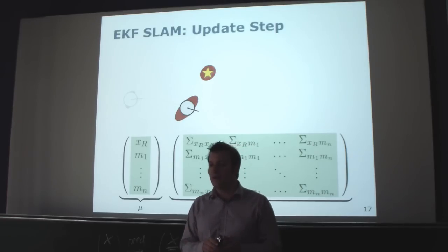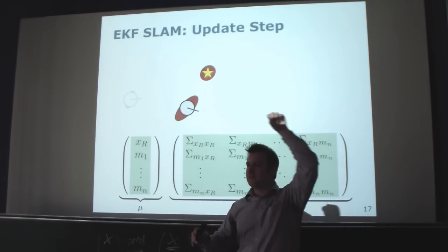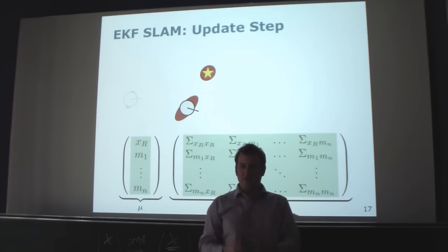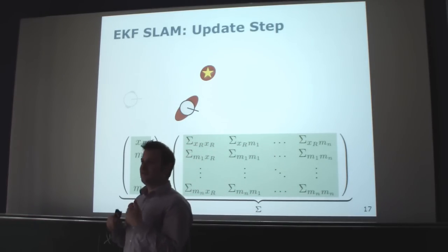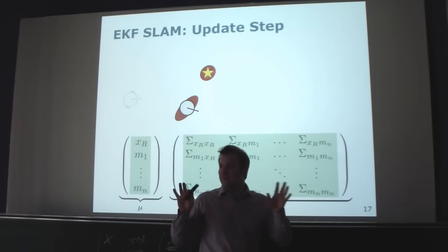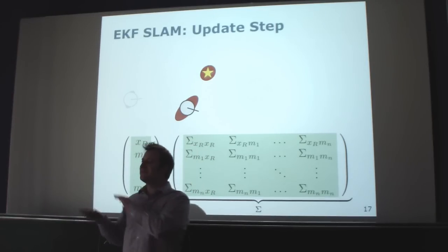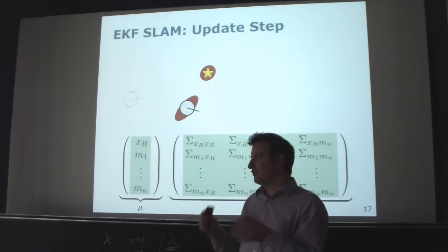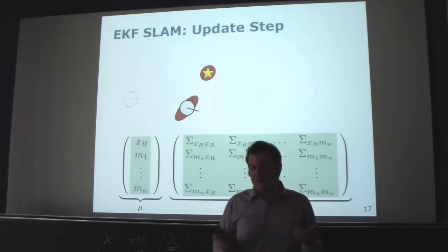On the other hand, tracking all possible data associations is very complex because you have a huge tree of possible data associations which expands, and for every node of this tree, you would have to maintain its own Kalman filter. So it gets very, very costly very quickly. That's the reason why most people just do a nearest neighbor data association, or they have some feature descriptor, where the sensor tells me this trunk looks gray, this trunk looks more black, so maybe different trees, something like this. But treating this in a very general way leads very quickly to a huge number of possible data associations. It's computationally intractable to maintain all of them. And so typically you have to make approximations in this context.